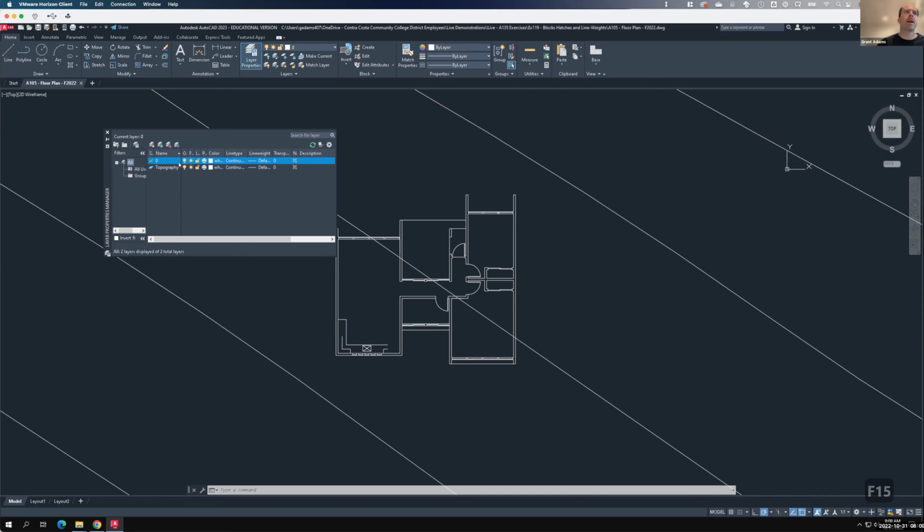So the first thing is that we have, and I'm going to use the topography layer as an example because you'll start to see what happens on the screen when I do this. So we have the layer. It's not an active layer because it doesn't have a green check mark on it. It's not the current layer. We have the layer name, that's topography.